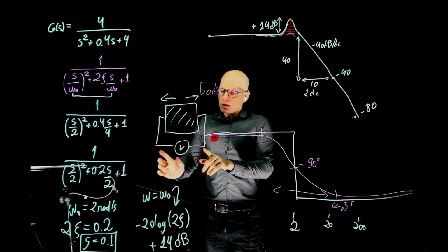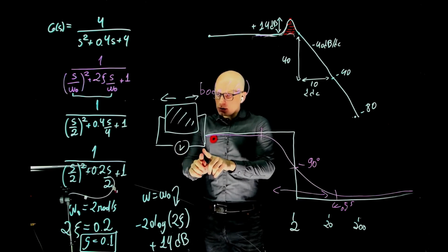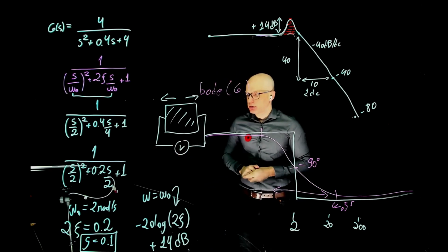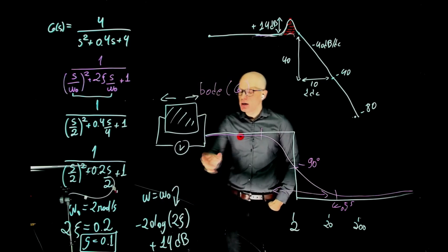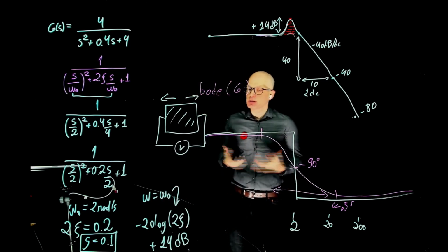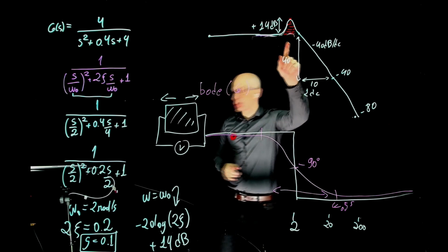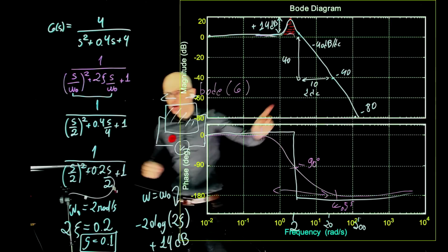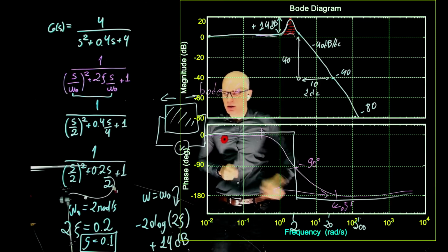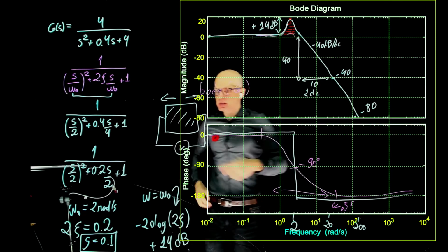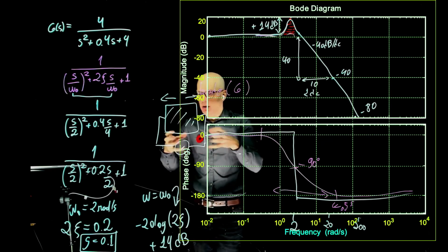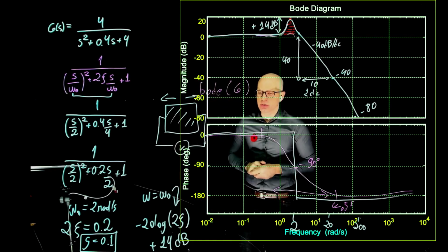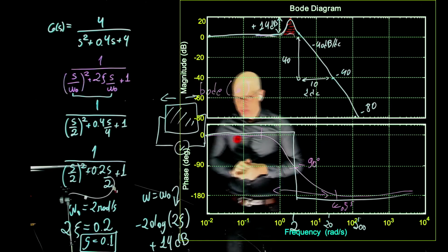So clearly here, we want to work very close to the resonance frequency, and we want a damping ratio that is the smallest possible. Why? Because we want to maximize the output displacement. We want to be operating close to this peak here. The input to the system would be a voltage, and the output would be the displacement of the piezoelectric actuator, of this kind of ceramic material.